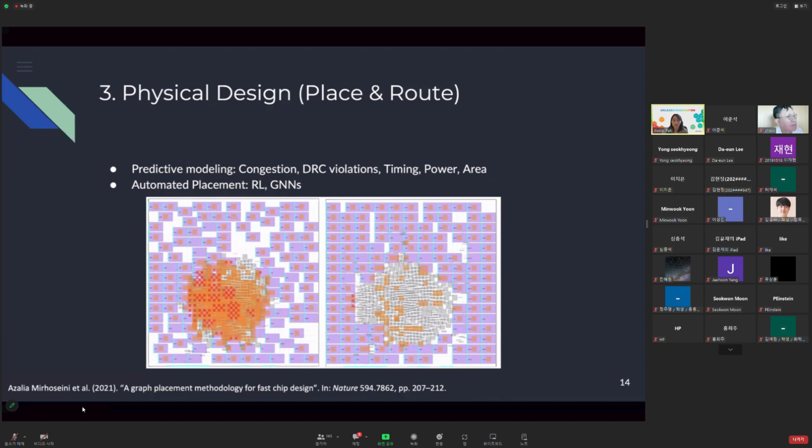So at that time, the problem that we wanted to solve with the AlphaChip work was how to place the macros. Here, the macro means the bigger blocks. So you can see smaller blocks like the gray things here, and then the bigger blocks, purple blocks. The purple blocks are so-called macros. And depending on how we put those macros, the whole performance of the chip can be changed.